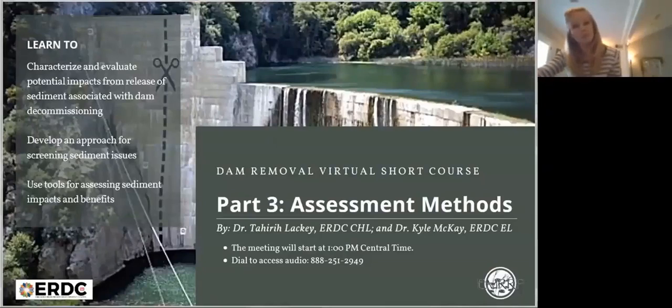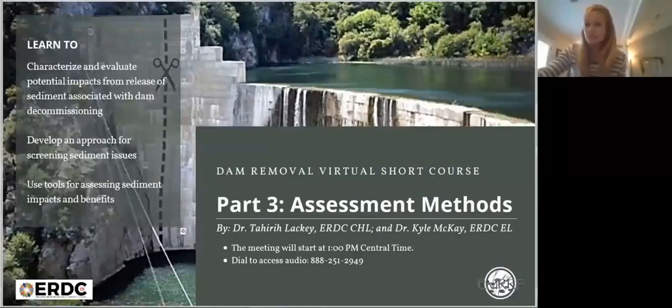Throughout the course, we've been learning to characterize and evaluate potential impacts from release of sediment associated with dam decommissioning, develop an approach for screening sediment issues, and use tools to assess sediment impacts and benefits. Today, we're going to continue with a focus on assessment methods, presenting an overview of techniques to assess sediment impacts with a focus on screening level techniques, including conceptual models and screening criteria. And then we'll have a case study demonstrating application of these techniques to assess potential impacts for stream barrier removal planned for Moona Creek, New York.